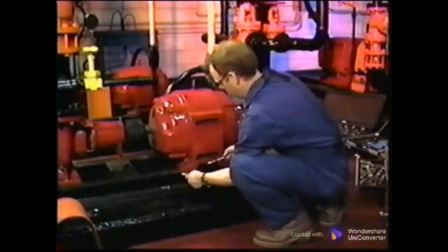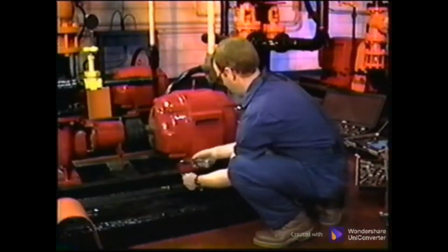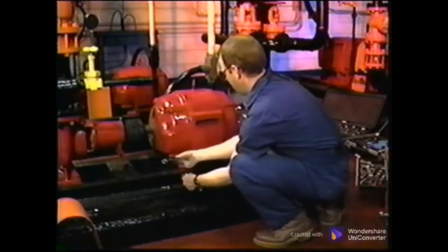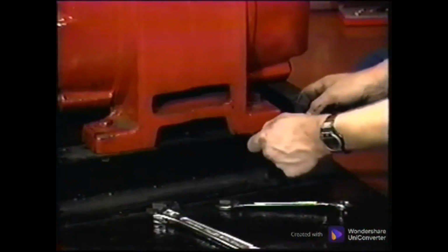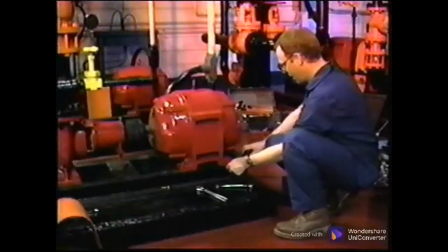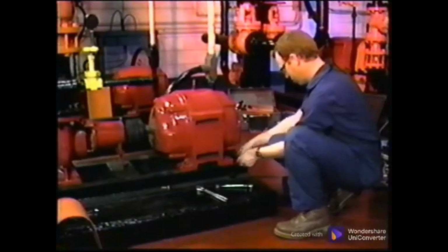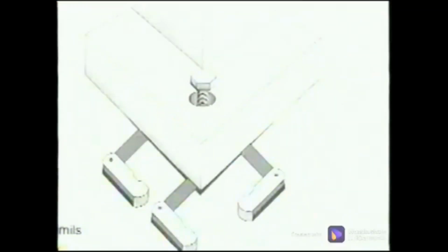The soft foot may be one that is bent down, bent up, or parallel to the base, but not touching. The soft foot could even be due to an untrue base plate. To check for soft foot, make sure all the hold-down bolts on the feet are loose. This is where science becomes an art. Use a feeler gauge to measure the clearance under each foot, increasing the thickness until the feeler gauge fits firmly under the corner of the foot.